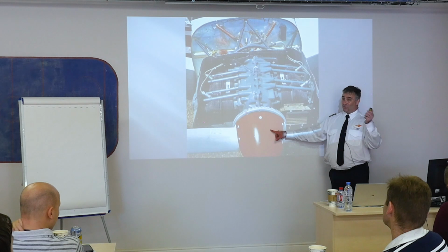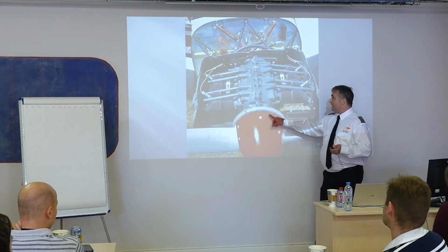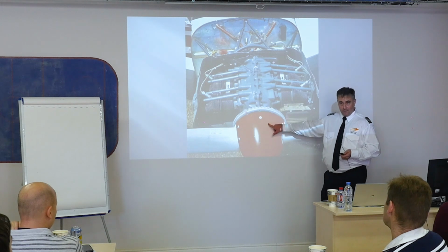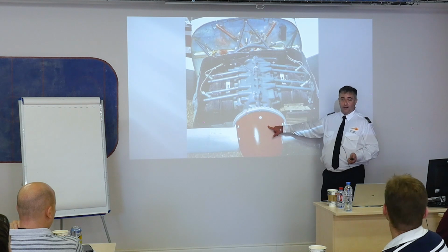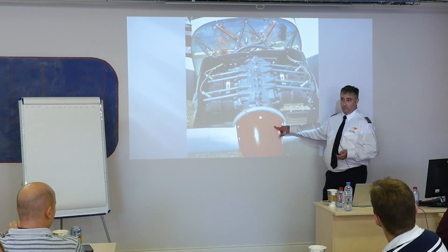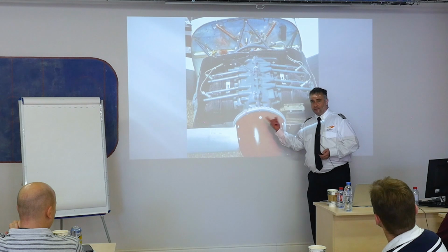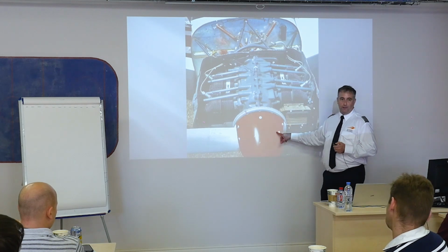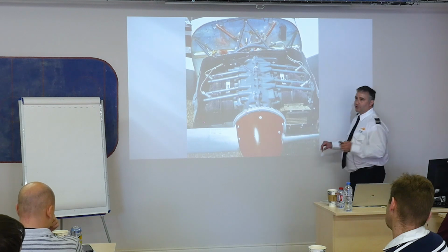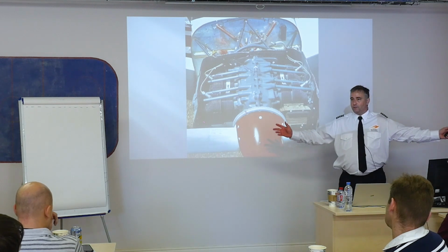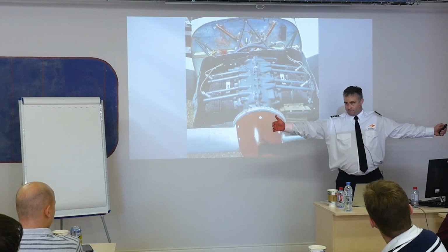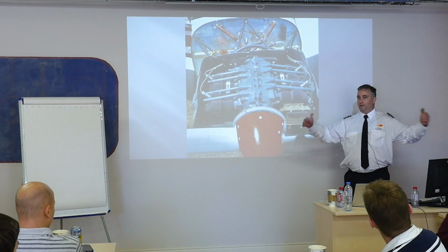Directly, and that is a great thing that you said that because it's bolted to that crank. Some airplanes, and we have one of these airplanes, have gear reduction. Means that the engine spins at one RPM, but then that RPM is reduced to the propeller. These propellers are generally 75 inches. So somewhere a little about 6 feet or a little more than 6 feet in diameter. Okay?